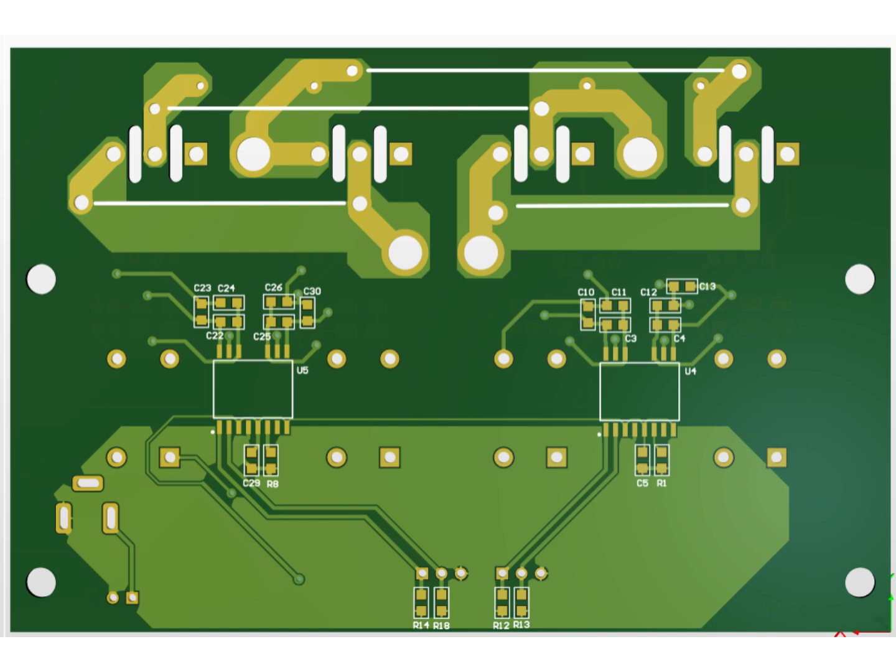This physical separation, combined with isolated gate drivers and isolated power supplies, ensures safe operation of the inverter, protects the low-voltage electronics, and improves noise immunity in a high dV/dt switching environment. Overall, the layout reflects a clear isolation philosophy, which is essential for reliability and safety in high-voltage inverter and motor drive applications.